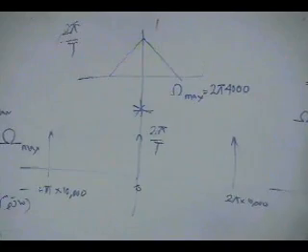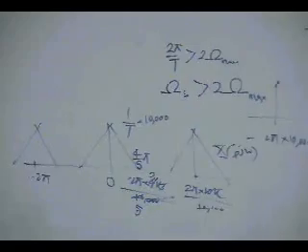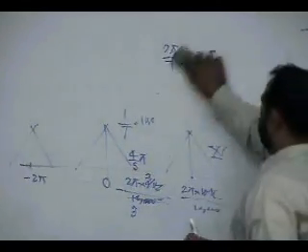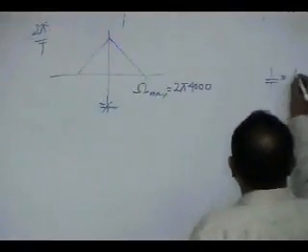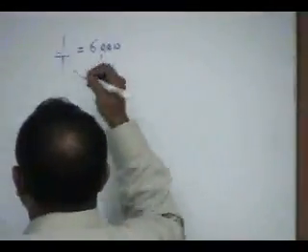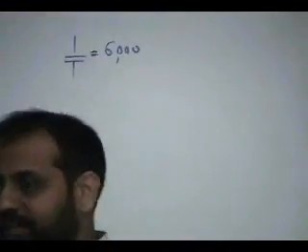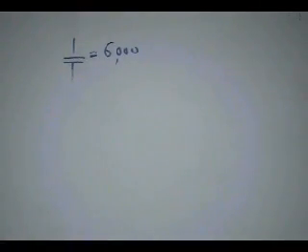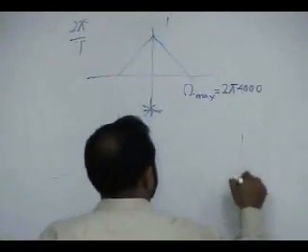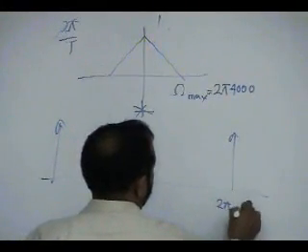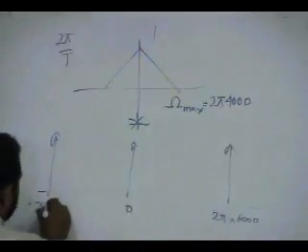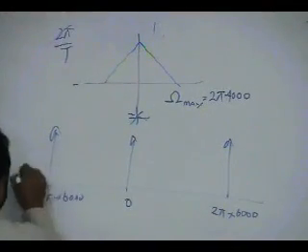Okay, so aliasing will happen if you don't sample fast enough. If I say, okay, sample at 6 kilohertz, what will happen if you sample this at 6 kilohertz? 1 over t is 6,000. So 6 kilohertz means that you now have an impulse here, an impulse here, an impulse here: 0, 2 pi into 6,000, minus 2 pi into 6,000.